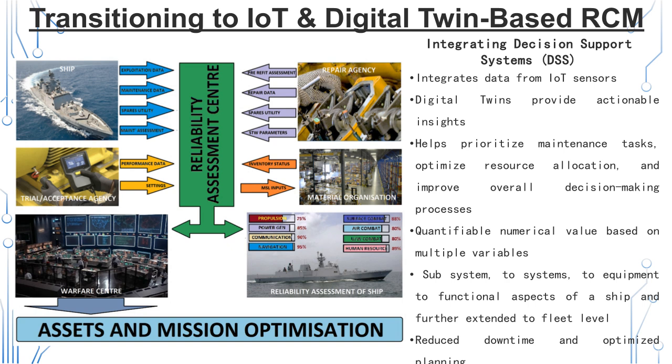Though there are reliability engineering studies which can give quantitative assessments, here the qualitative assessments will actually do a good job. This numerical value, which may be called reliability or a modified reliability number, is defined from subsystem to systems to equipment to functional aspects of the ship, and further can be extended to the naval fleet. So this gives a near real-time assessment of the assets at various levels, facilitating decision support based on realistic situation rather than intuition or perception.